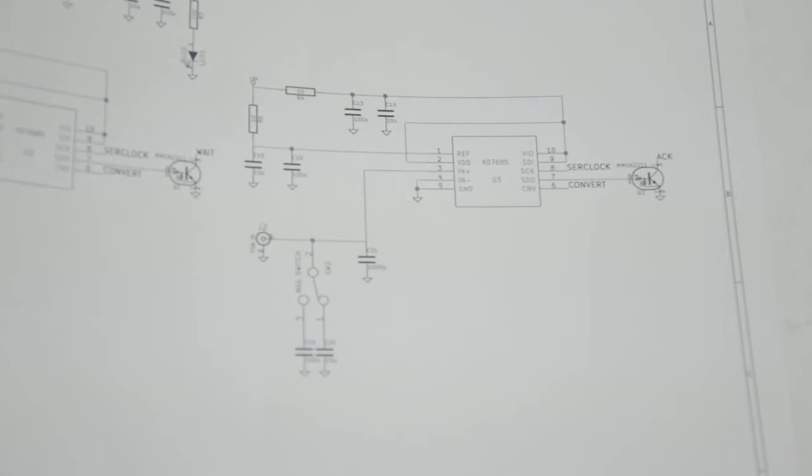The reason for that is, I actually haven't mentioned that before, but you can build this spectrum analyzer in different levels. The first level is a basic spectrum analyzer. The second level adds a tracking generator, and the third level adds a VNA option that allows you to do filter testing and things like that.